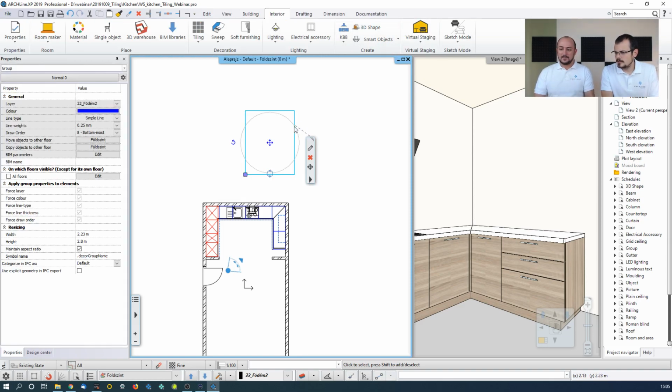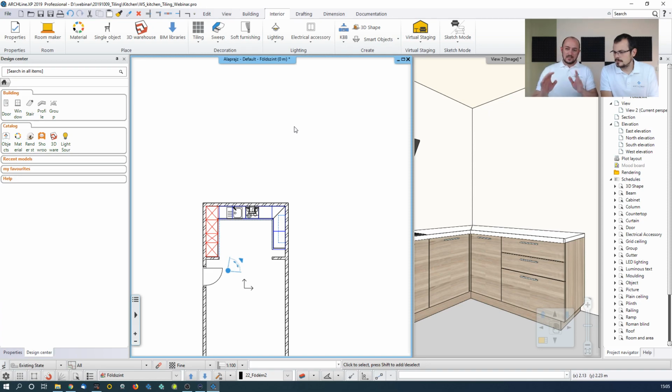And at any time you can erase, simply just select it and remove the layout from the 2D. It won't remove whatever you have in the 3D surface. This is an automatically generated dynamic drawing, like when you have some sort of section or elevation view or something like that. When you close the elevation view, the building does not disappear. So this is the same behavior here.